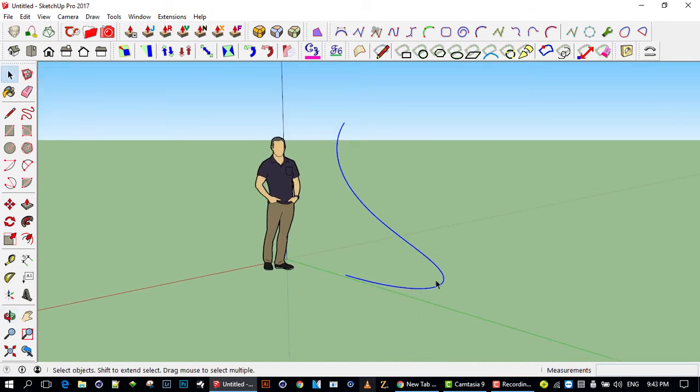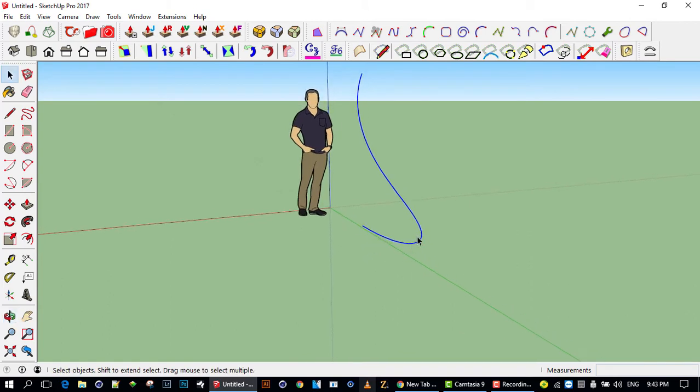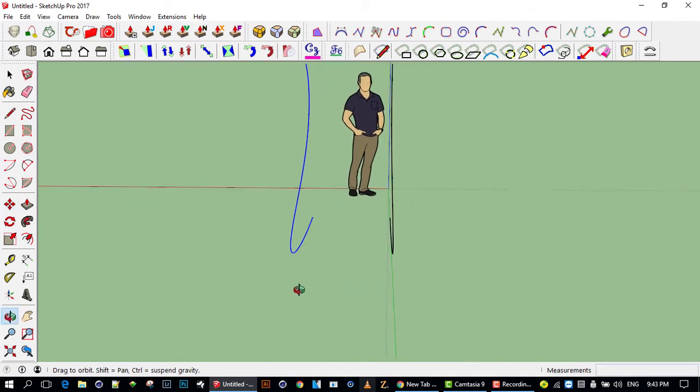So I'm going to create a loft, which is going to go between two of these similar sections. So I've selected that one, press M to move, and then if I want to create a duplicate, we do the same thing I showed earlier on, press Control, and you'll see a plus sign come next to the move tool. Then because I have this item selected and we're in move mode and plus, which is to create a copy of it, I'll then left mouse button and drag it along the axis. So I'm going to just drag it a little bit this way, maybe just about a meter. The reason I know it's a meter, it's showing here at the bottom, or I could just type it in.